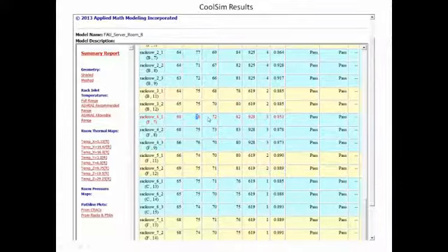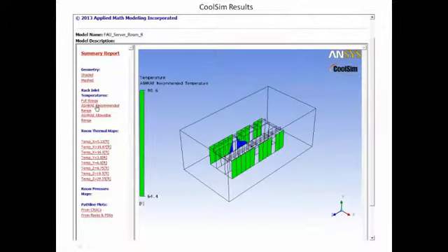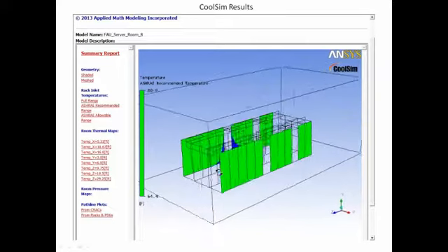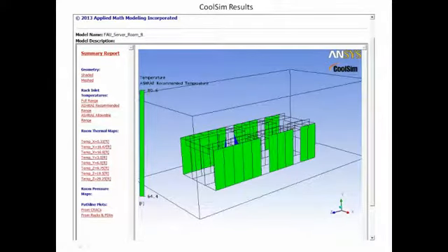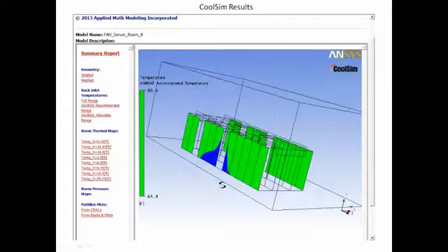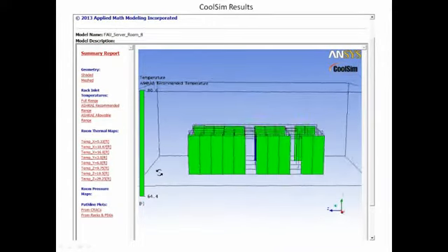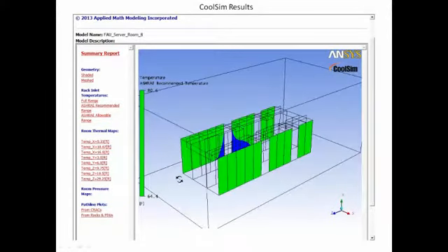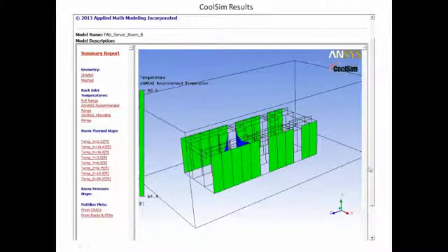It's a little hard to digest a bunch of numerical data, so we also provide it in terms of color. And these plots are relatively new. We've done these in CoolSim 4. Here what I've done is taken the range of acceptable temperature for rack inlet according to Class I server specifications, and I've made it green. And if you're too hot, then it's red, and if you're too cold, then it's blue. And you see, in general, this data center is conforming pretty well at its base level to the specification set by the ASHRAE standard, even though I've got an imbalance of airflow.